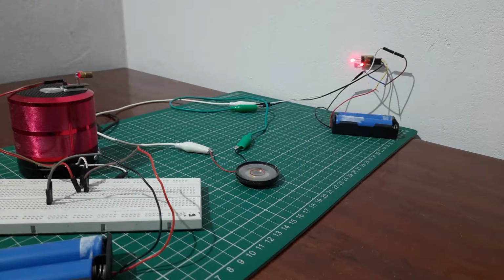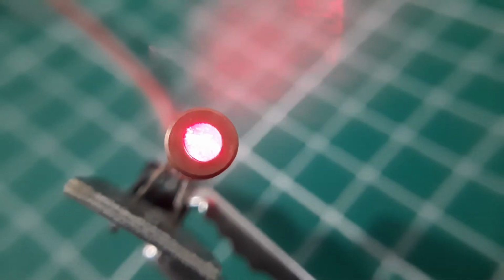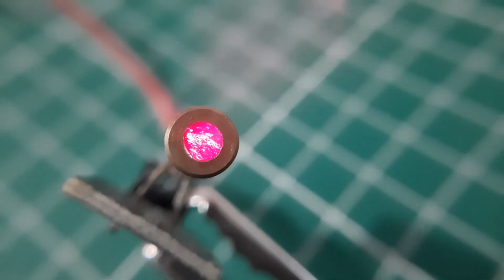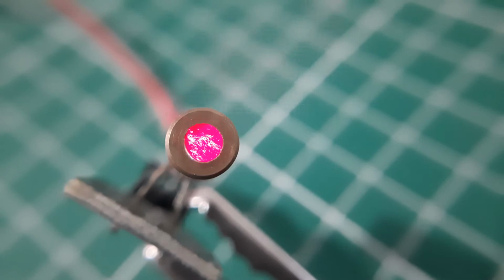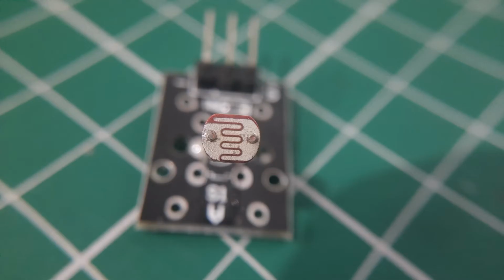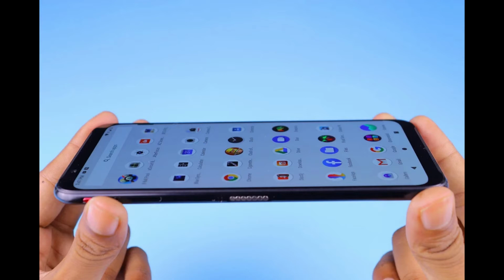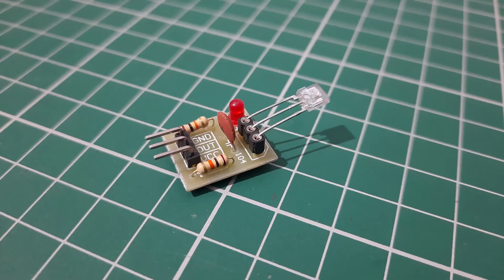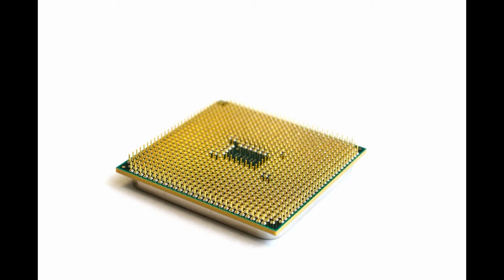It consists of two units, the transmitter and the receiver. Using light as the medium, the transmitter sends an analog signal. The receiver unit consists of a photosensitive element like a photodiode, LDR, etc. The receiving unit is connected to the device to which the data is transferred. When the light falls, the photosensitive element in the device detects the change in amplitude or brightness of the light and sends it to the microprocessor for further processing.